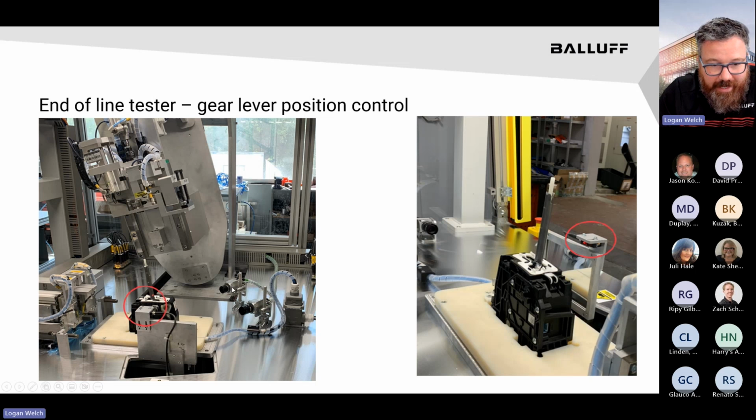And you can see over there's cameras and stuff, and we're doing all kinds of stuff in this test hub. But instead of putting a camera on the other side or putting some type of mechanical switch, we're using a very cost-effective photoelectric sensor. And that's doing the lion's share of the work because of how this test assembly works. It needs that rod in different positions at different times. And again, this is doing error proofing, and I would just say process control all in one with a small photoelectric sensor, where in the past it might be using another camera on the other side. I think actually that's what it did. It replaced a camera mounted on the other side here.